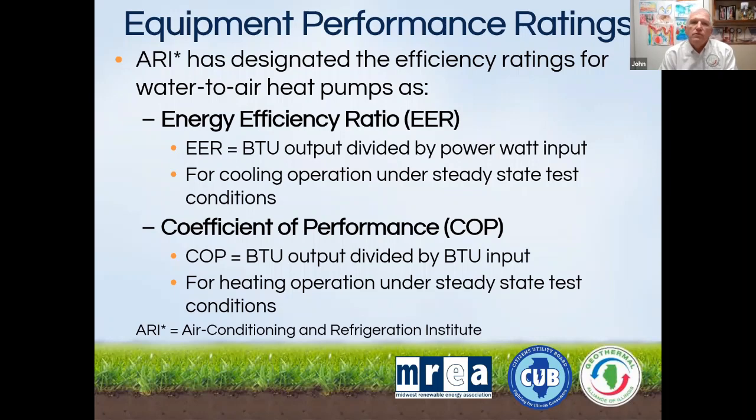Why don't we use SEER for geothermal? Well, we don't use SEER because there is no season underground. Underground knows no season. It's the same year round. Once we get down 6 or 7 feet underground, it's the same in December as it is in January, as it is in July. It never changes. So we use EER because it's steady. That's the beauty of geo. And then in heating, we use coefficient of performance, or COP. What you should remember with both EER and COP is that the higher the number, the more efficient the system.